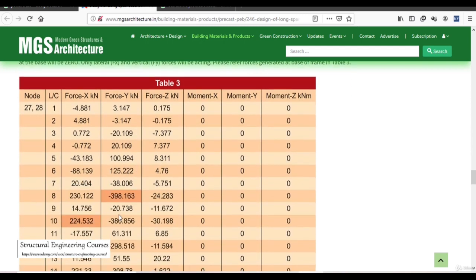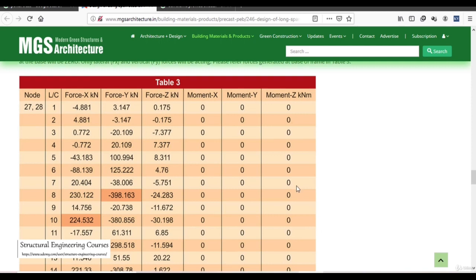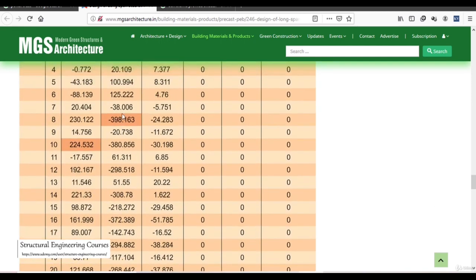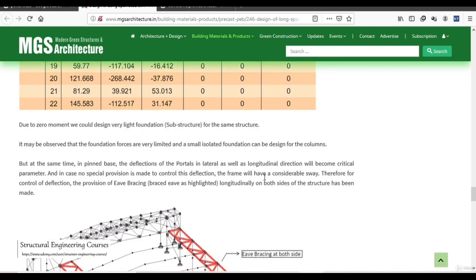Here it can be seen that when we are designing these foundations for the vertical reaction only, only this 398 kilonewton force is coming on the bottom. It may get increased to 450 kilonewton, let us say 45 ton, and this horizontal force will also contribute to the sizing calculation, because this horizontal force on the top becomes the bending moment at the bottom of the foundation. This is another important concept that can be read in soil books, how you can design foundations for horizontal reactions.